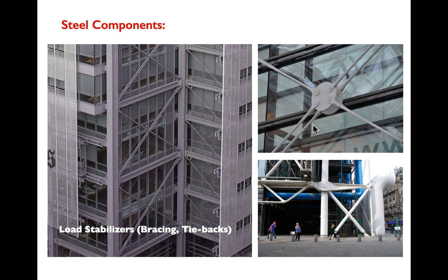One material doing a bunch of different things. Tension here. The pins clearly are in shear. The plate is going to always be in tension in one direction or another. And because we can form it in so many different ways, and because it's equally good in tension and compression, steel works in all of those situations, right? One material, several different functions.